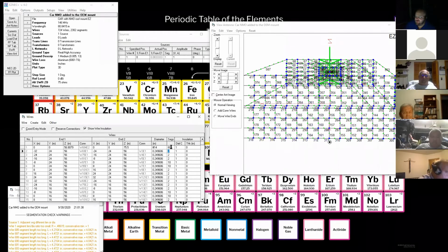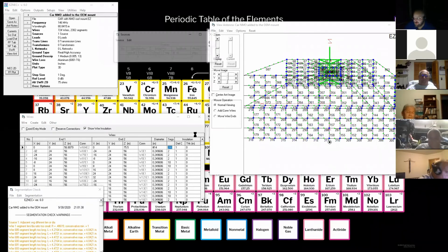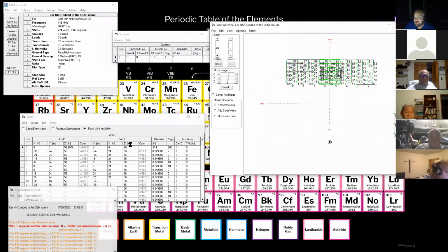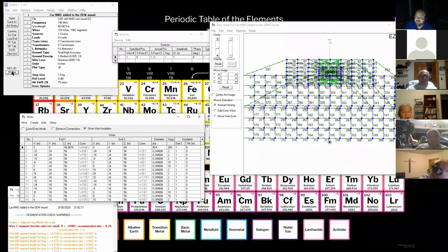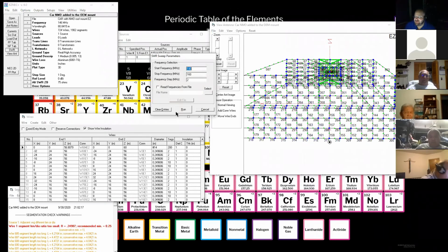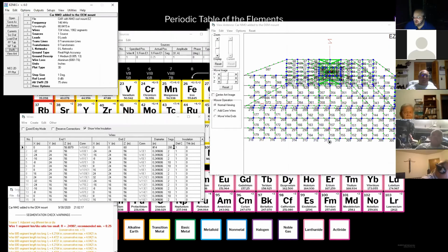There's another mode of failure that you're going to run into here. So I'm actually going to scale this back to 200 so we can actually calculate it. But I'm also going to shorten my antenna up to very short. And I'm going to run it again. How did I pass the geometry check? Oh, it's because my connecting plane is wrong. All right, I'm going to jump out of here and open a different model where this will be easier to show you guys.